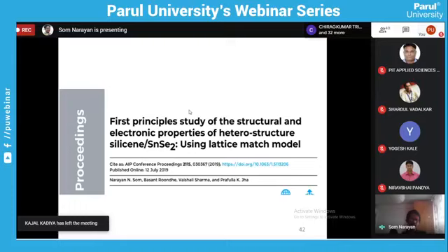Yes, the band gap is increased by 0.01 eV or 0.05 eV with the use of GeS and PtS2, but still it is not that much for optoelectronic properties or for other applications. So we go for SnSe2, and the lattice mismatch of silicene and SnSe2 is 0.18%, which is lesser. So we can use a lattice-matched model for preparing their heterostructure.